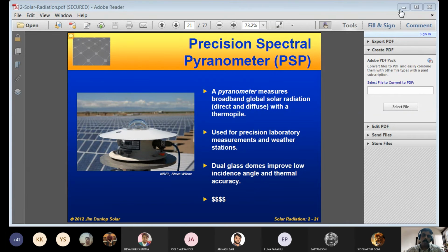So a 1 megawatt plant exposed for 1 second will produce 1 megajoule. For 1 hour, multiply by 60 into 60. It is rated at peak power, but always we cannot expect 1 megawatt. Solar radiation is fluctuating, so we have to take an average value per day. How much PSH, peak solar hours, we can get, like that you can calculate.